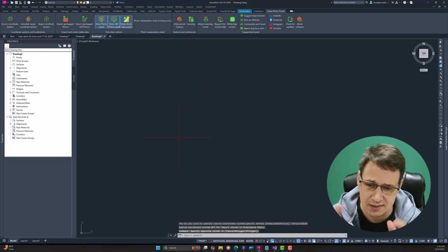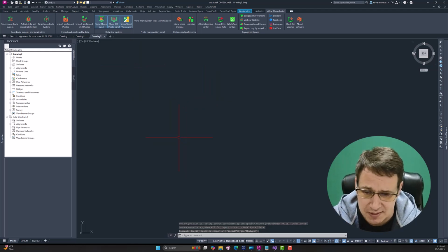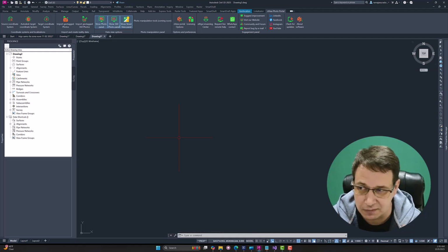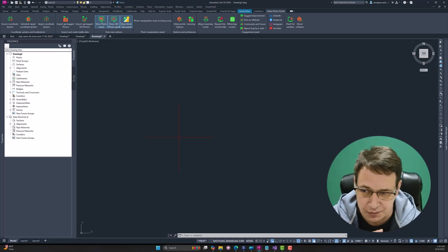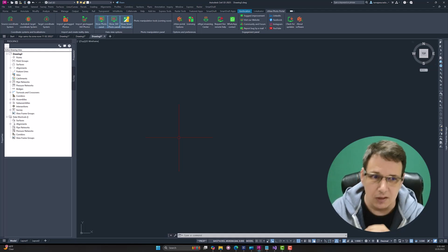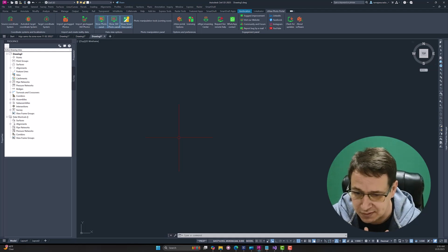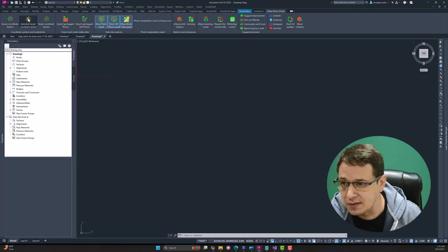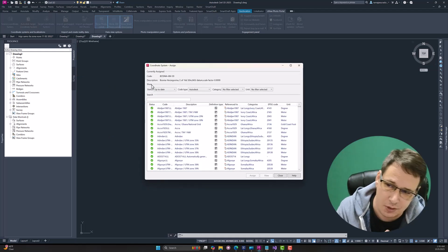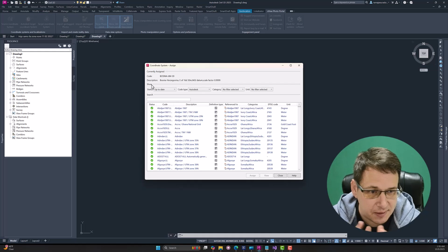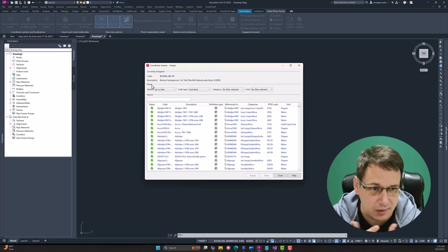So this data source coordinate system is set in the CAD file itself. So there is no need for extra files, and it will be much easier and much more maintainable for you to use. The next step is to set the CAD project coordinate system, or Autodesk target coordinate system, and we decided to go with the Autodesk database because it's already built in, and you can also use the base imagery from Autodesk.